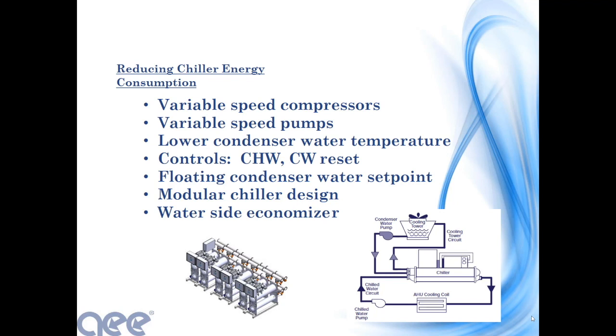Well, what you're doing then is you have a chiller at 100% load operating at the top of that curve, and a new one coming in, also at the high end of that curve, where a better strategy would be to let that first chiller go up to 50% and then bring on the second chiller to 50%, so that when you're at 100% load, you have 2 chillers operating at 50% at the bottom of that curve, rather than one operating at the top of that curve.